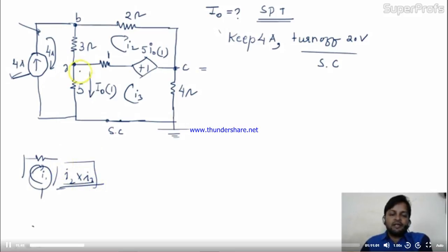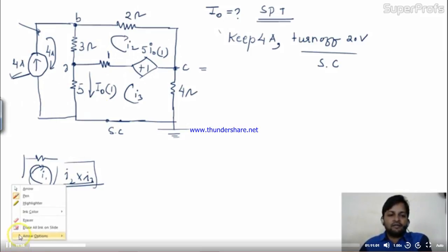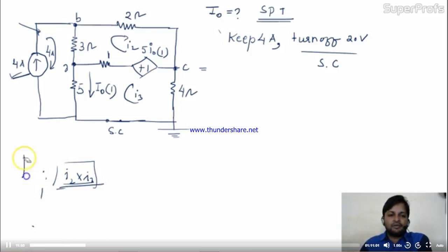So doing this circuit by KVL, we encounter 2 variables. The same circuit, if we do by KCL, we will have 3 variables. So better to go with KVL. Is it okay? I hope.